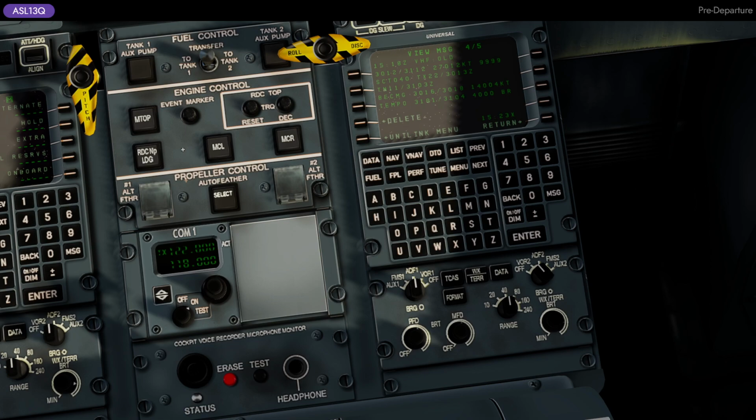Now this can be interesting, because between 4 and 6 p.m. it can become 140 at 4 knots, with of course TEMPO between 1 a.m. and 4 a.m. tomorrow, which we do not care about. So in our case, if it's going to become 140 at 4 knots, I'll opt for ILS 12, and then if needed we can switch the direction. We'll take RIGMU 2 Kilo, ILS 12, DEVDA.